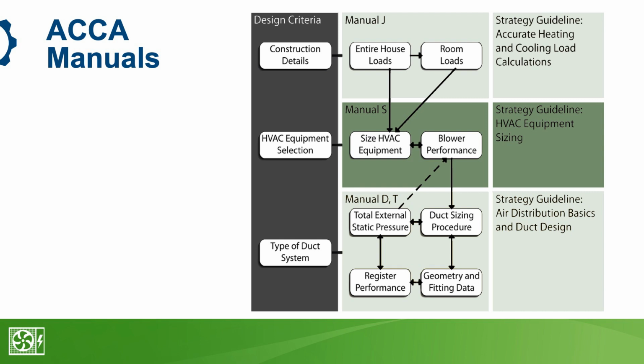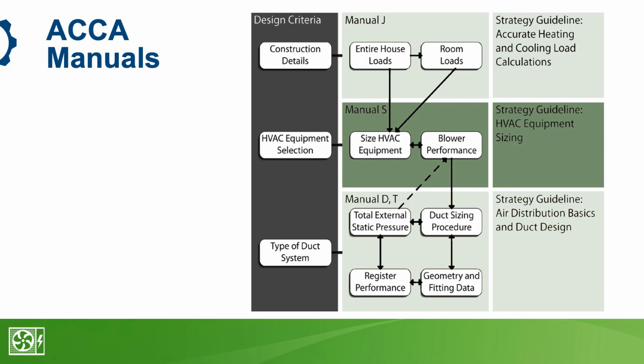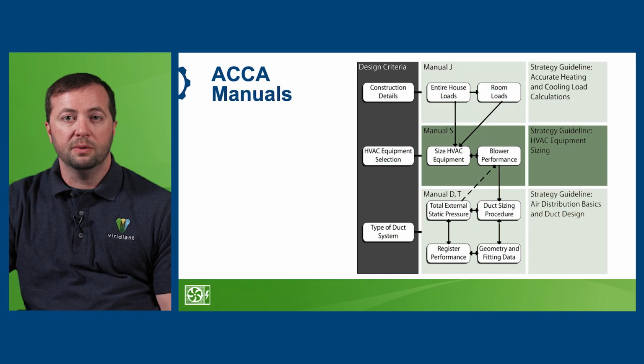such as heat movement, airflow, solar gain, etc., to precisely calculate the home's heating and cooling demand, select equipment based off of that, and then create a duct layout that's best going to help the home meet those loads. It starts with sizing, and that means selecting equipment with heating and cooling output that matches the needs of that specific home. Just choosing equipment based on square footage, or that seems to be just a little bit bigger just in case, it's not smart.